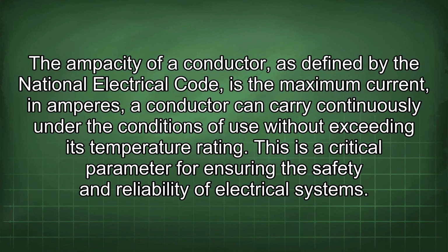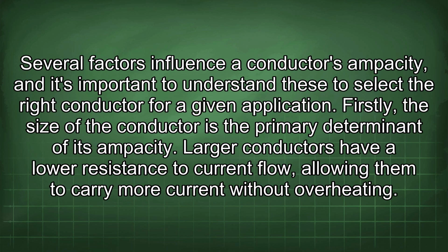The ampacity of a conductor, as defined by the National Electrical Code, is the maximum current in amperes a conductor can carry continuously under the conditions of use without exceeding its temperature rating. This is a critical parameter for ensuring the safety and reliability of electrical systems. Several factors influence a conductor's ampacity, and it's important to understand these to select the right conductor for a given